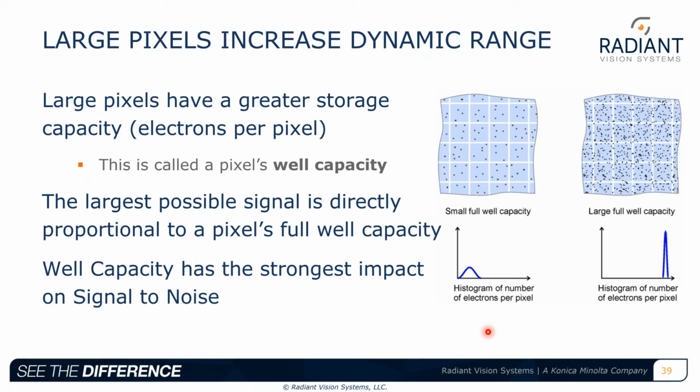As I was mentioning, dynamic range is signal to noise. So the first thing you want to do is try to minimize all of your noise. To do that, you can cool the CCD. With all CCDs, you're going to have some thermal electrons, heat electrons that come in and look like signal, but aren't actually real signal from your device.